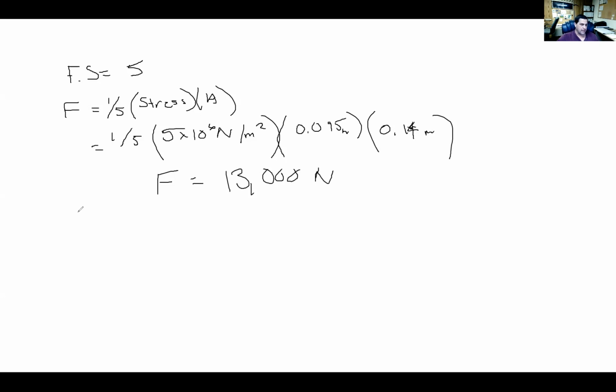So now what I need to do is figure out what I can apply. So I'm going to sum torques about some point has to be equal to 0. So you can pick which end of the beam you'd like. I'm going to choose the left edge of the beam. So I've got one of these roof supports, FL. That's 1.2 meters away.